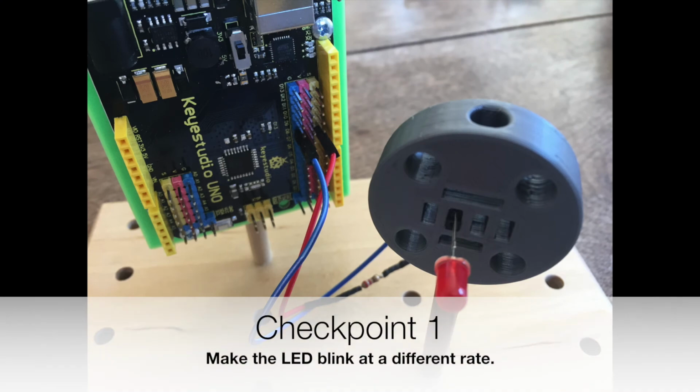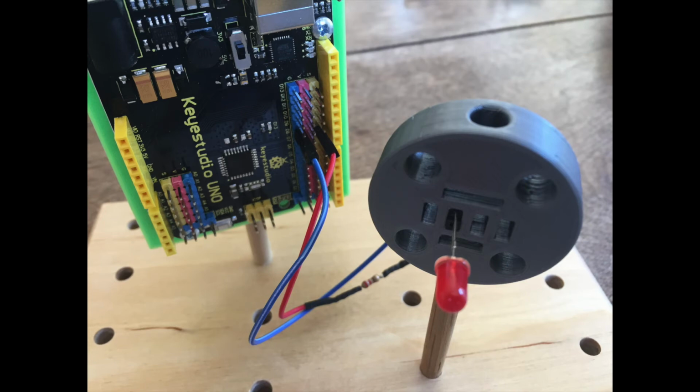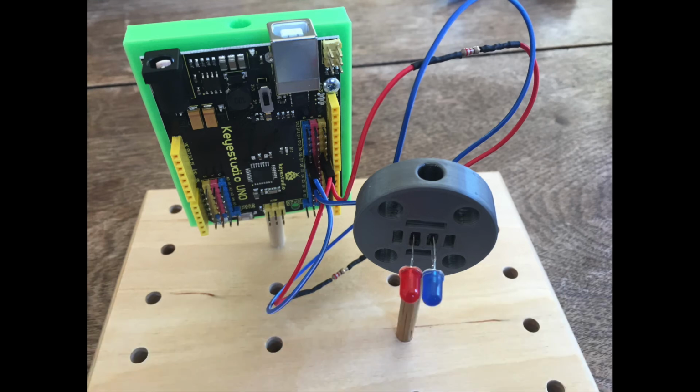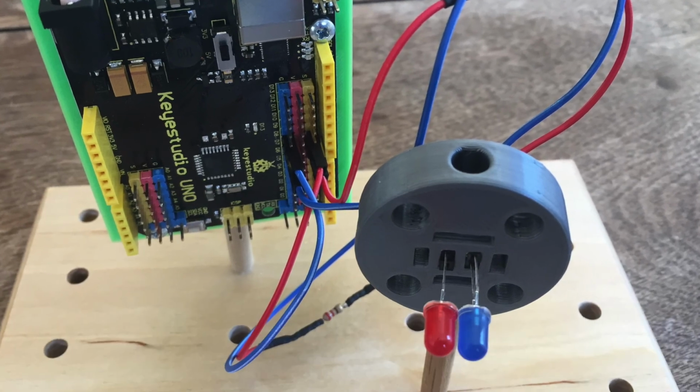Checkpoint 1. Now try changing the delay value in your sketch to make the light blink faster and slower. Checkpoint 2. Add a second LED circuit to the digital pin of your choice. Change the code so that the two lights blink alternately. Checkpoint 3. Make the lights blink together.